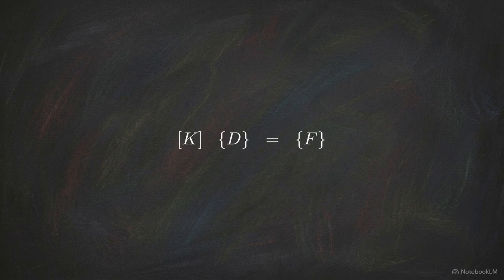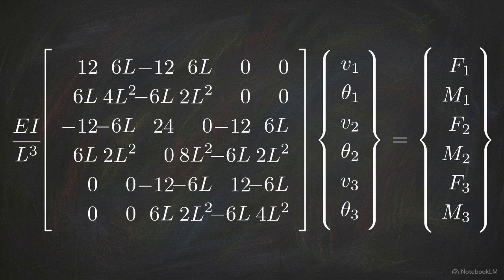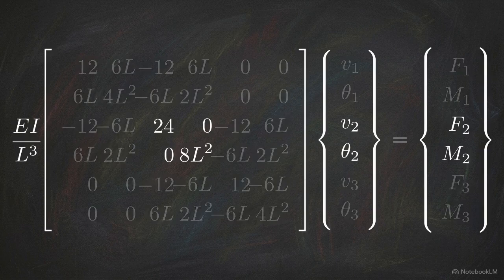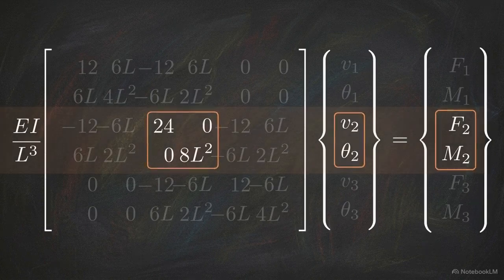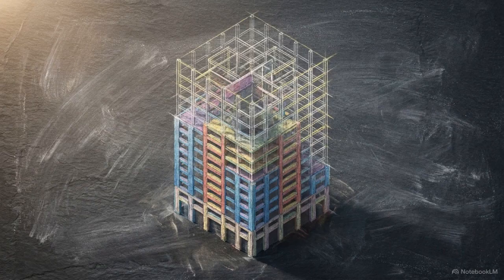This completes the structural equation, KD equals F, where the fully populated global stiffness matrix is set against the global force vector. The final array contains distinct zones, independent terms on the edges, and centralized zones defined by joint mechanics. The merger of these isolated arrays creates a single, indivisible mathematical model that mirrors the behavior of a physical structure. This assembly algorithm, mapping local variables to global arrays and applying superposition, scales to any engineering problem, from a two-element beam to a skyscraper simulation.